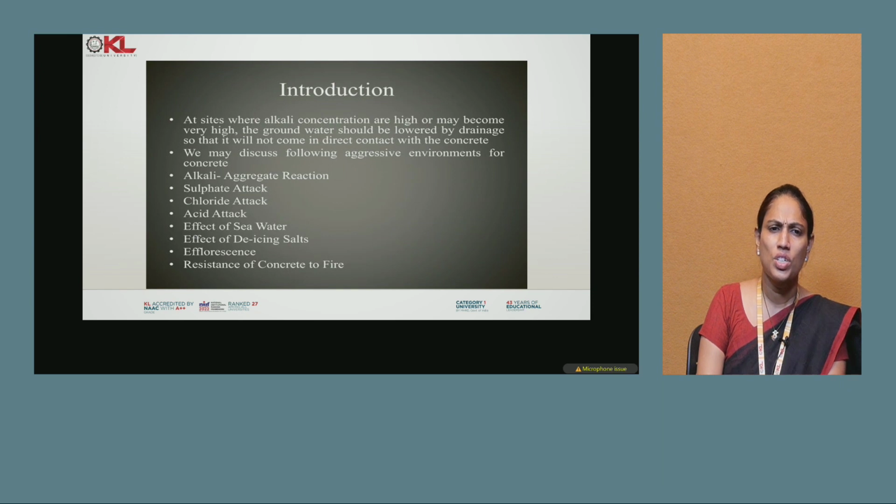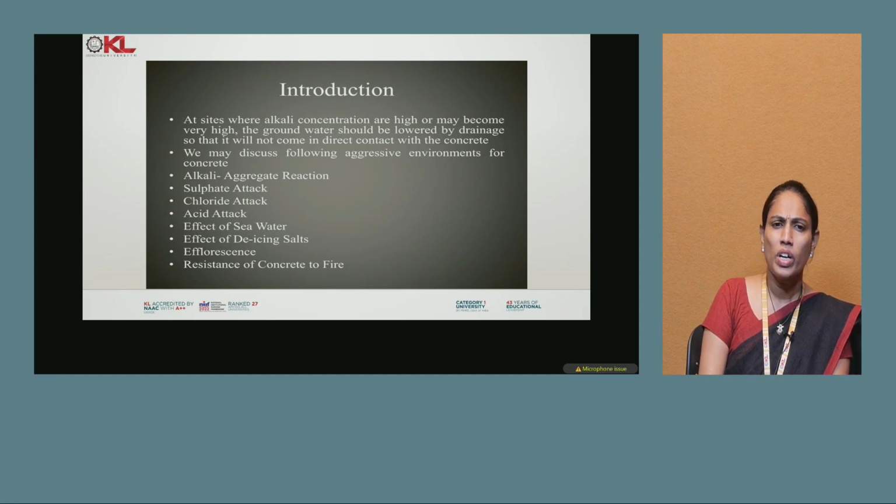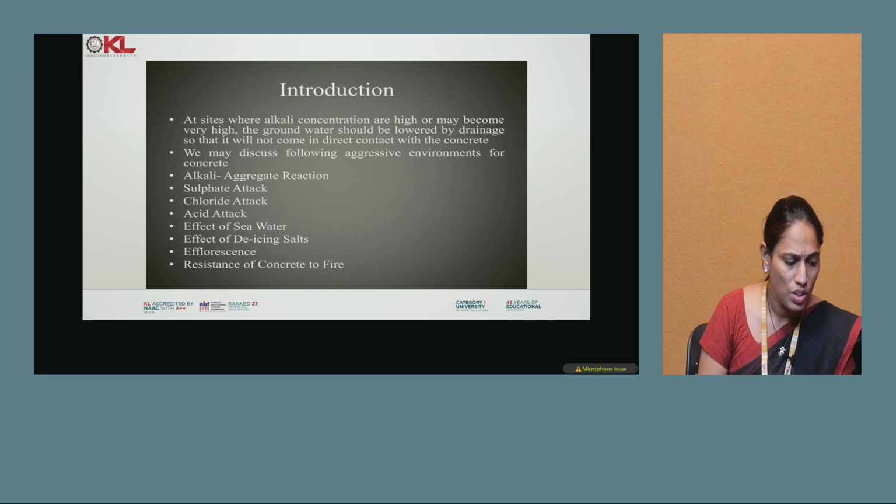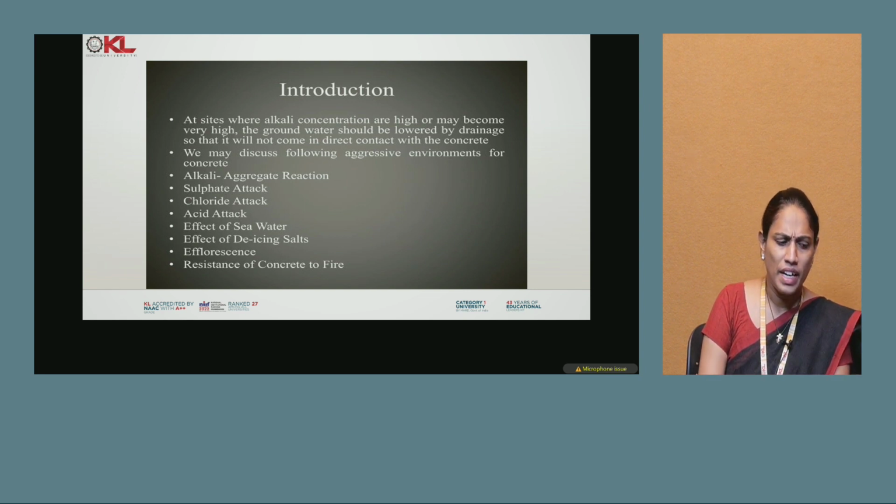In the introduction, at a site where alkali concentration is high or may become very high, the groundwater should be lowered by drainage so that it does not come in direct contact with the concrete. We may discuss the following aggressive environments for concrete: alkali aggregate reaction, sulfate attack, chloride attack, acid attack, effects of seawater, effects of de-icing salts, efflorescence, and resistance of concrete to fire.